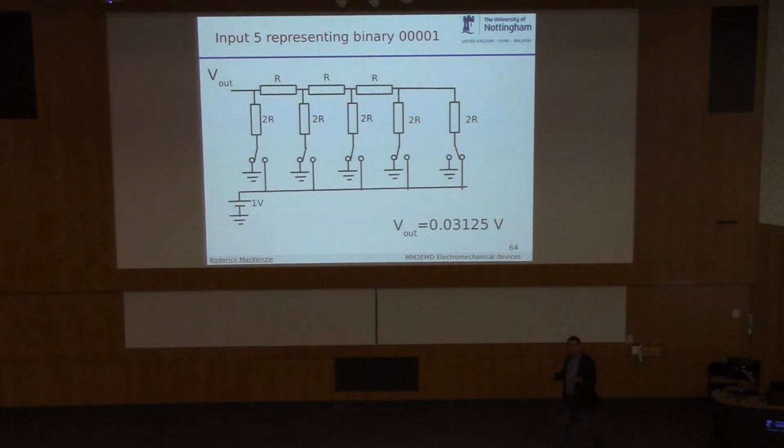to the output. So it's just a bit like a binary number, in that this is the most significant bit. This gives the most voltage, and this is the least significant bit and gives the least voltage. Each voltage that you can put on the output pin with each switch halves in value each time you go from here to here to here to here. So this is looking like an incredibly useful circuit if we want to go from the binary world to the analog world, and in fact it is.